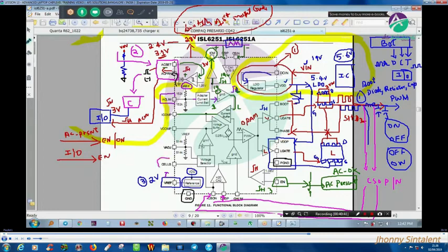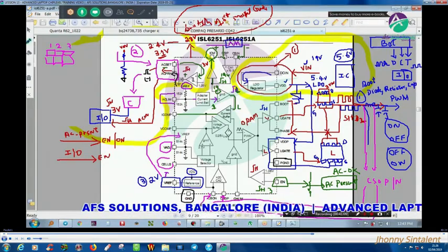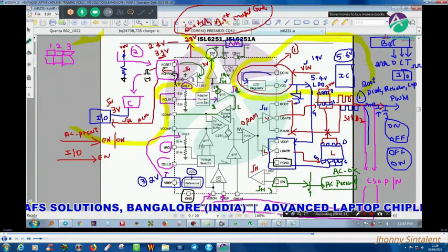Now you got the point. So this cell voltage adjustment, with the help of the reference, the same reference here, will adjust the voltage. That means in the battery we will have 4 cell or 6 cell. Every cell should not charge at a time. It will start step by step. First this one should charge, second the second cell has to charge, third the third cell has to charge.